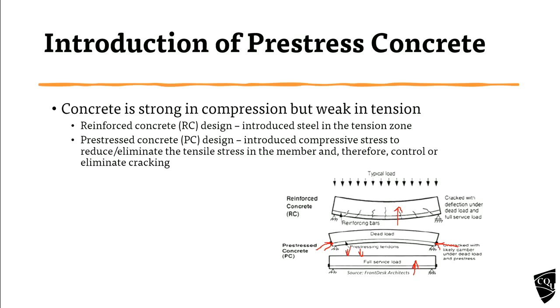So the initial upward deflection will reduce the overall or final deflection of the beam. So in pre-stress beam, we will have very less deflection under service load. When you put the service load, we will have very small deflection compared to RC beams.